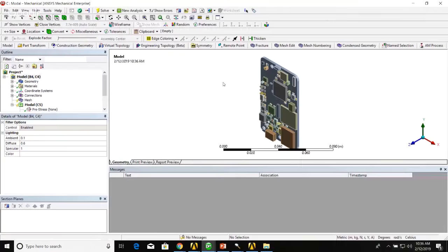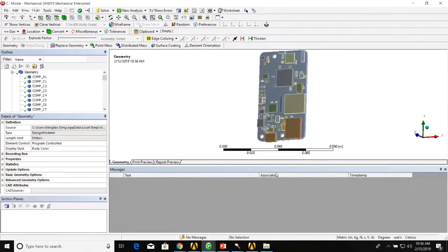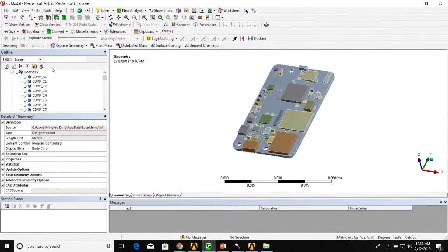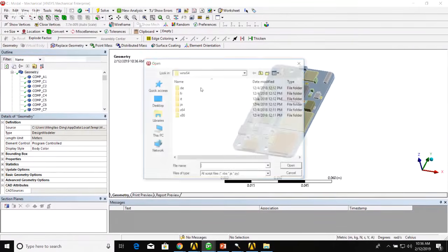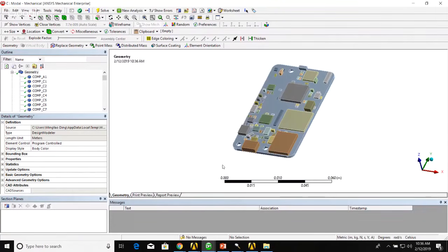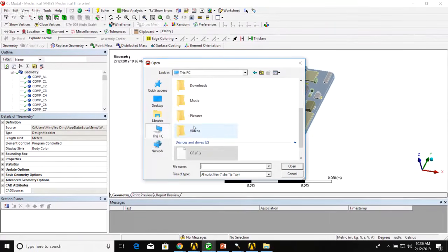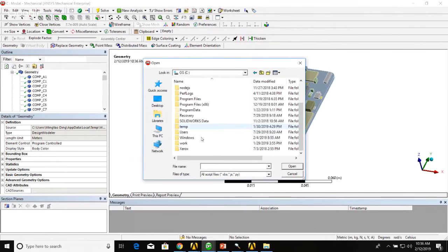Yeah, this is my modal analysis. As all ANSYS users know, by default, we have structural steel assigned to everything. Again, if I have a 2,000 part assembly, assigning all the components carefully takes a lot of time. So with DfR Sherlock, we can just run a macro. That's not it. Try that again. The macro is created alongside everything else. So let's go to where I put this.